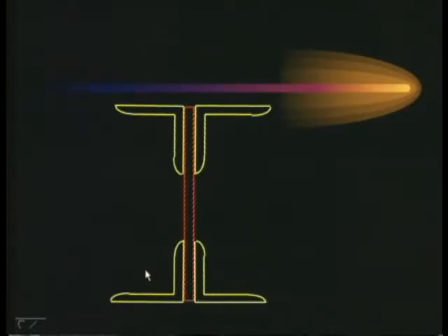See this? This is a plate girder. What is the difference between the previous built up section and this one? There you had an I section, a rolled steel section we have used, but here there is no rolled steel section. You have a vertical member. Can you just make a guess about it? What is this member called? Web plate. This member is called a web plate. You have 4 angles. Ultimately, it takes the shape of an I, but it is not a rolled steel section. You have a plate and some angles.